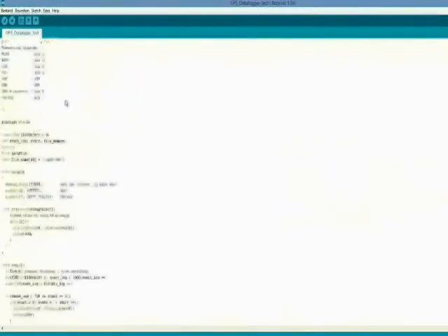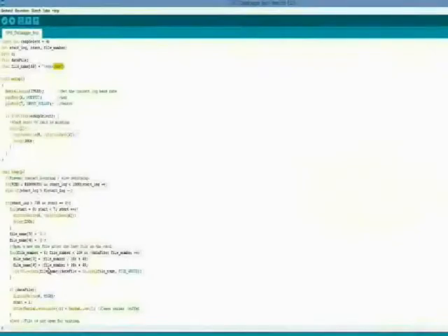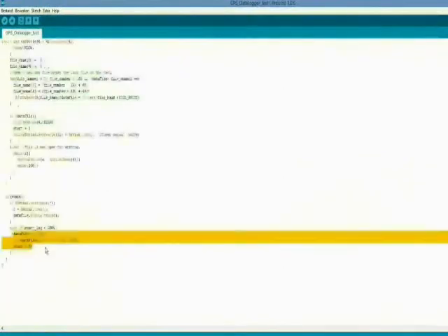Gate level simulation methodology: the Verilog simulation with back annotated delays, VHDL simulation, VITAL compliant VHDL models, and back annotated delays. Verification tools supported are Avanti, Polaris, Cadence Verilog XL, Leapfrog, ICOS, Mentor Graphics ModelSim, QuickTurn, and Synopsys VCS, as well as Vera.